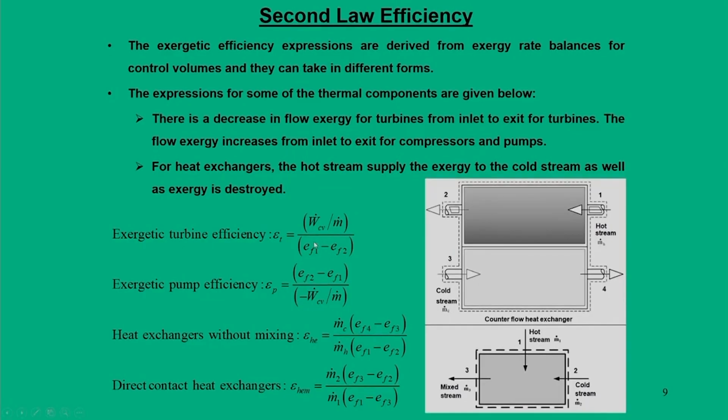For this irreversibility part, exergy calculation is very vital, which we call exergy auditing, or the proper utilization of energy resources. Based on this concept, we define exergetic turbine efficiency. A turbine is a work producing device, so the work term, that is work flow per unit mass, is at the top. In the bottom part, we have the difference in the exergy due to flow in and flow out.